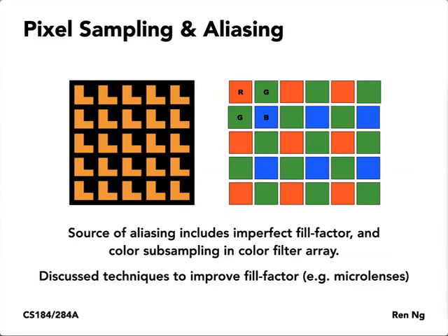And so we know from our theory on sampling and anti-aliasing that once aliasing is in there, it's very difficult, if not impossible, to remove it. So we have to anti-alias this somehow. And the prescription for anti-aliasing in a general sense was to filter out the high frequencies before we sample, right? Filter out high frequencies above the Nyquist rate before we sample. Okay, so how would we do that?